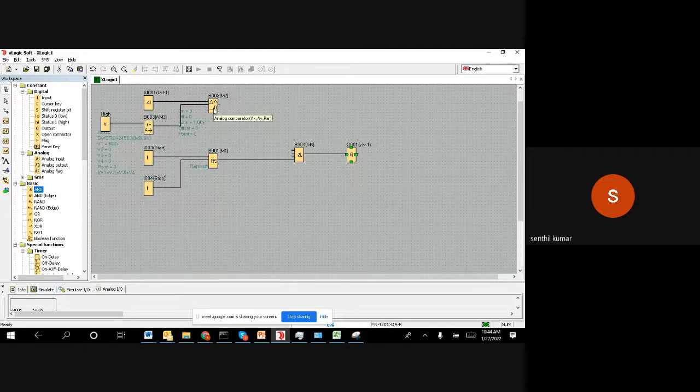That's the meaning, right? If it's 1,000, that means the liquid did not come to the main reactor. If it is less than 500, that means the liquid from the first tank has transferred to the main tank. So that's why, when I'm starting, you open this valve provided my first tank level is above 500. That's the logic I made.